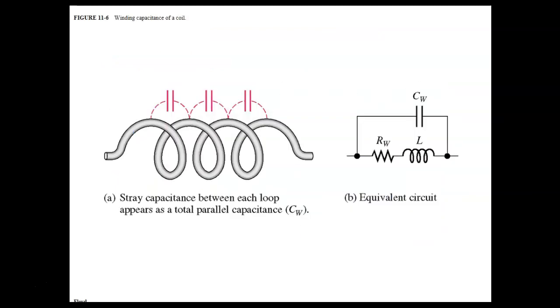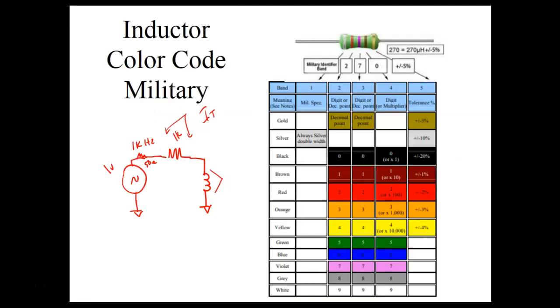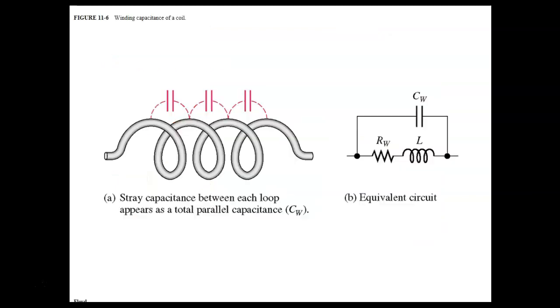So this is not some old stuff, guys. Both of y'all are in the electrical trade, and that's something y'all need to know. So if you ever get the opportunity to wire a house, mark those breakers. All it takes is an instant just to put where these go. But they don't do it. They just don't take that time.